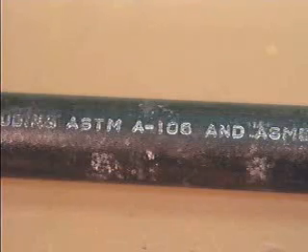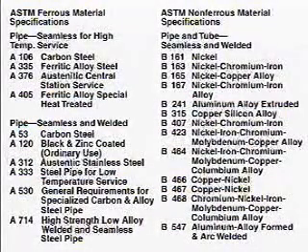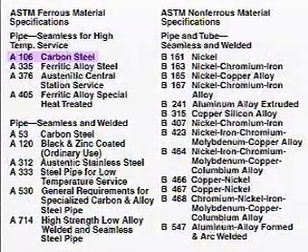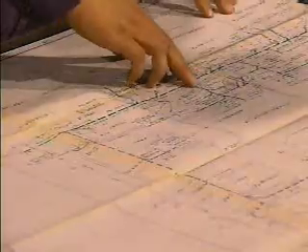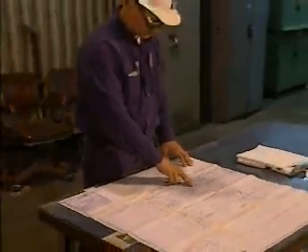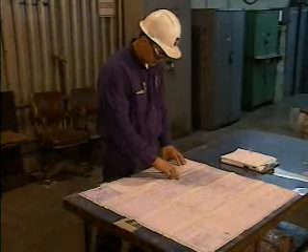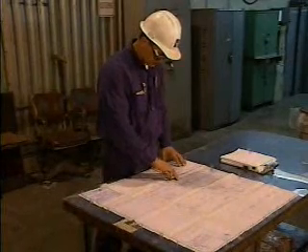For example, this pipe is printed with the ASTM identification number A106. This identification number indicates that the pipe is made from the ferrous metal carbon steel. The ASTM or other identification number for an individual pipe in a piping system is usually listed on piping specifications and project blueprints. Maintenance of piping systems can include performing routine inspections of pipes and pipe fittings for wear and damage.